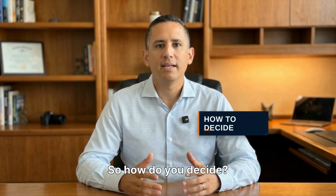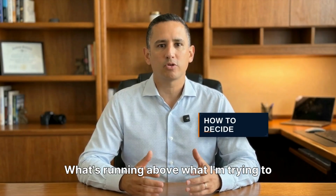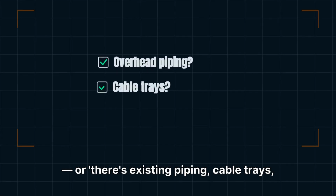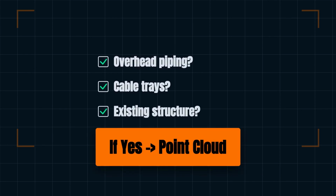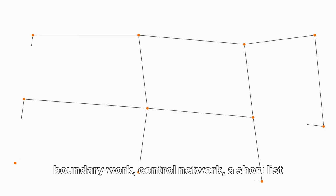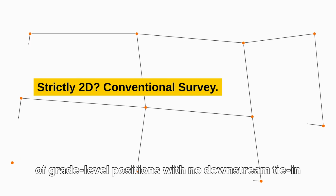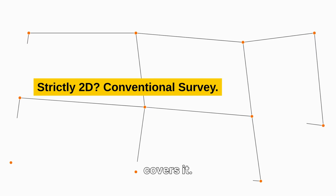So how do you decide? One question cuts through it. What's running above what I'm trying to tie into or modify? If the answer is I'm not sure, or there's existing piping, cable trays, and structure I haven't fully inventoried, a point cloud is the right foundation for that work. If your scope is strictly 2D, boundary work, control network, a short list of grade level positions with no downstream tie-in or modification work, conventional survey probably covers it.